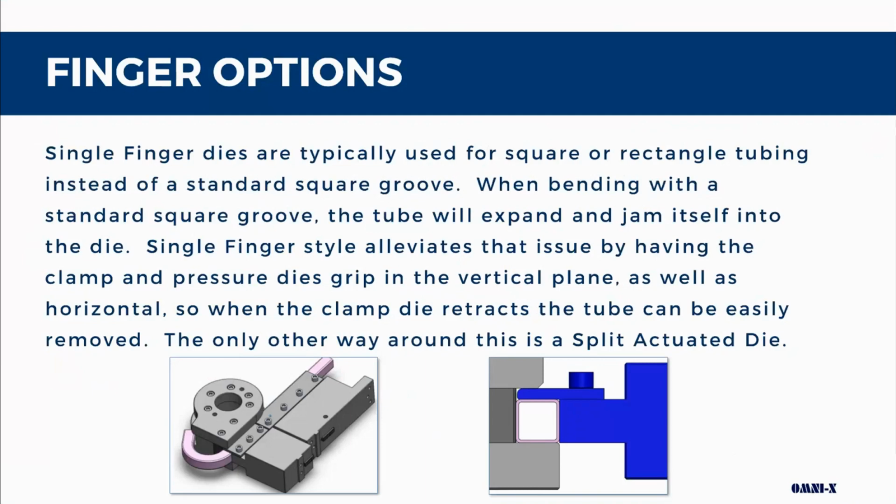Depending on the application and bender configuration, the finger can be straight or tapered and can be positioned on the top or bottom of the tube.